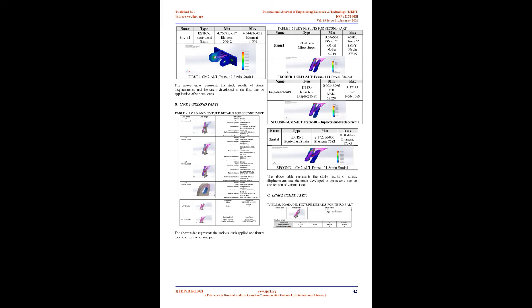Motion analysis. Motion analysis is generally employed to accurately simulate and analyze the motion of an assembly while incorporating the consequences of time and motion study elements. This includes forces, springs, dampers, and friction. The study combines time and motion study elements with mates in motion calculations. Consequently, material properties, motion constraints, mass, and component contact are included within the solver calculations. This study analysis also calculates loads, which will define load cases for structural analyses.